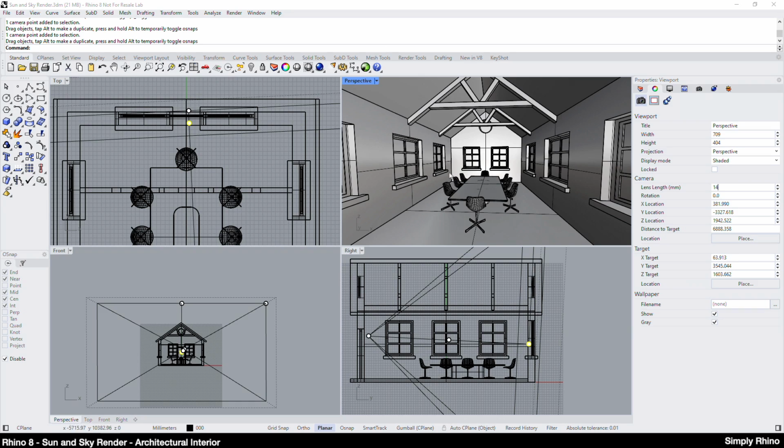Now, Rhino has a 2-point perspective projection that can be enabled to correct this, but I would suggest that it's easier to manipulate the camera whilst using the ordinary perspective projection, and then switch to the 2-point perspective when the view is pretty much set up.